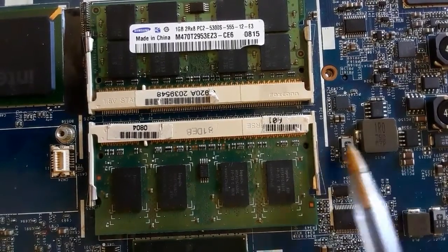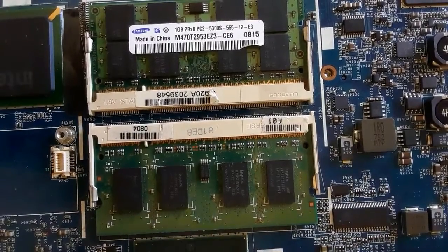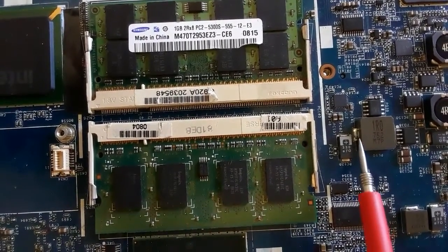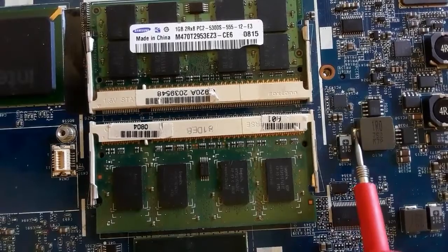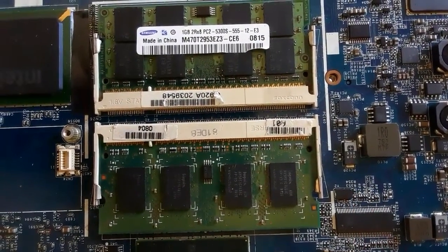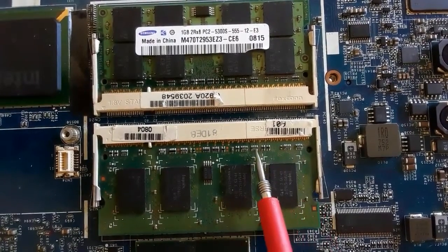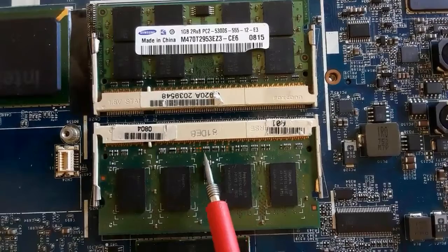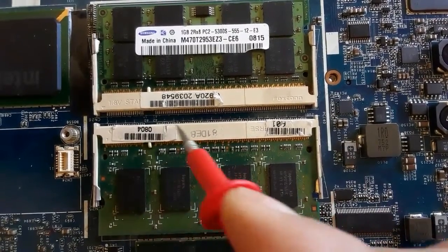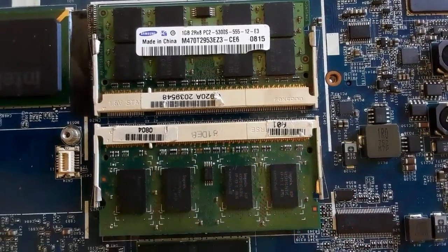So now let's see in the motherboard. So here, if you want to check whether you have 1.8 volt or not, you should check the inductor, as you can see, the inductor or the capacitor. You will find 1.8 volt for DDR2. And the VTT, you will find it in terminals. For example, here, this is terminals. This is a network resistor. If you check these terminals, you can find 0.9 volt.